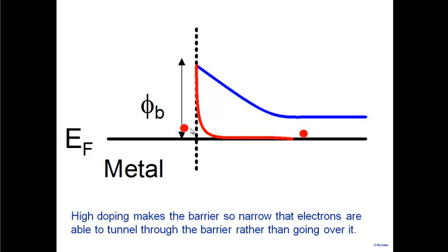How did we do that? By making it heavily doped. Heavily doped, the barrier becomes extremely narrow, and then the tunneling process starts to occur, and now you are able to get very low contact resistivity. So that's the trick that people use for making a very good contact. So if you keep doping small, it acts like a Schottky barrier diode.